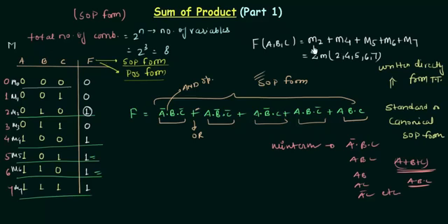There is no need to write it like this. You can easily use a summation that shows you are taking the sum of these min terms. Actually, it is the OR operator, but it looks like sum. That's why we are taking this summation mark. Don't confuse yourself with the actual sum. It is the OR operation, but we are using the plus sign, so it looks like sum. So in exam, the question will come like this, and you have to find out the SOP form, the minimal SOP form, by using this information.